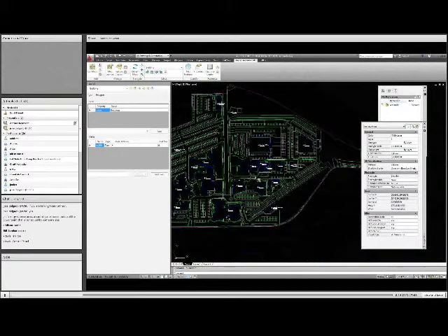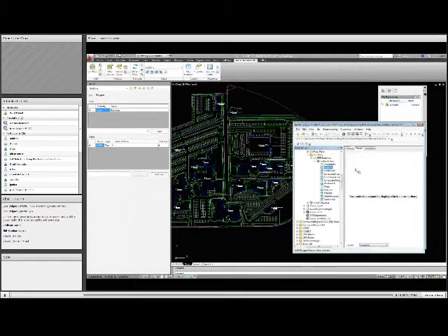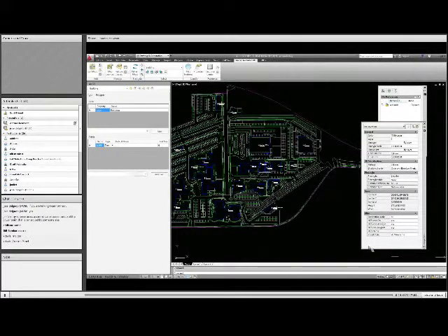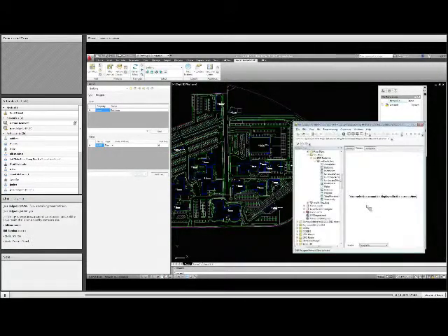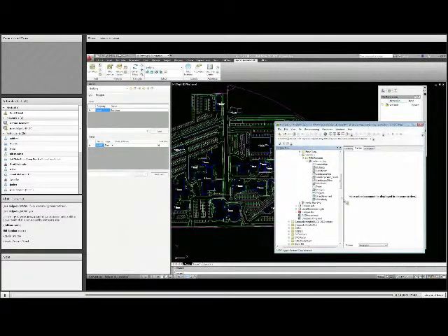With the room numbers as just plain text, I have another fun command that I wrote that will convert text to our standardized room number block. It finds all the text on that layer and converts that text into the room number attribute in our block. So here's all the data that we actually track for a floor plan. We have the building, the floor, the unique floor ID, which is the building and floor combined together, the room number, the unique room ID, which is all three of those put together, building, floor, and room. And then we also do the square footage.